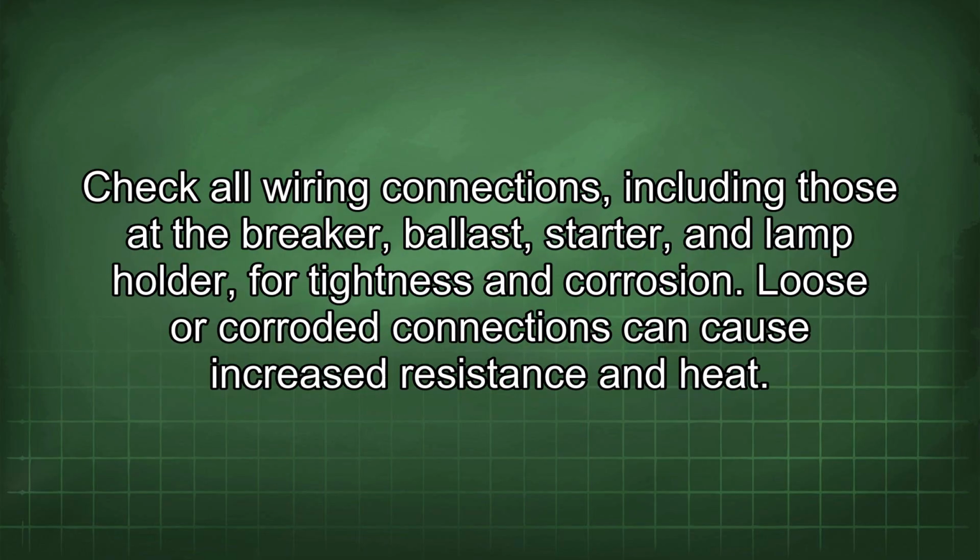Check all wiring connections, including those at the breaker, ballast, starter, and lamp holder, for tightness and corrosion. Loose or corroded connections can cause increased resistance and heat.